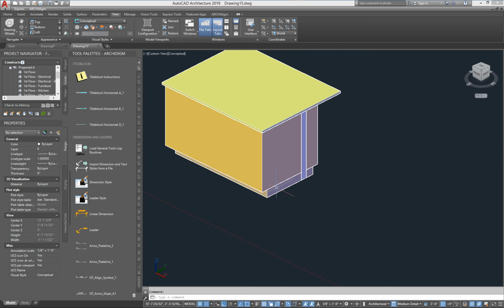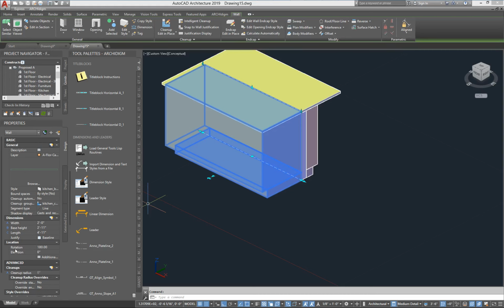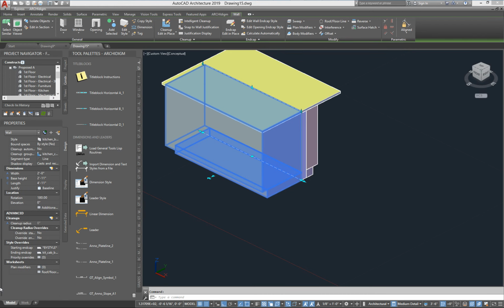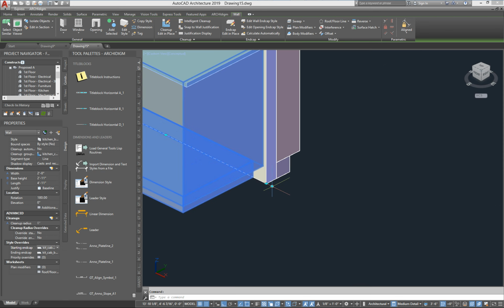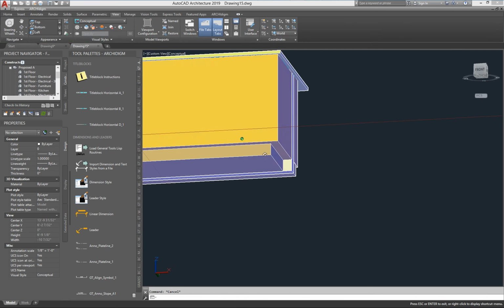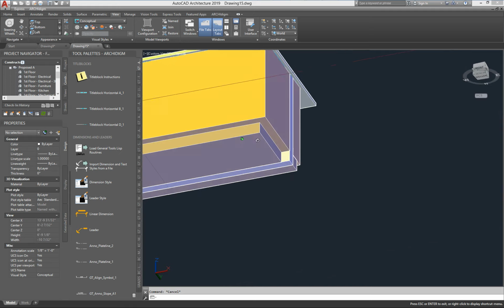But over here on this side, we'll select that. We'll run over here on our properties palette, and see here, by doing that insert and attaching it, we wound up bringing in that end cap. We'll just assign it to the other side manually. So where's the 25 there? And this will have the same problem with the 1 inch because it thinks there's a countertop. All right, but there you go. So that will give you the 3-inch kick.